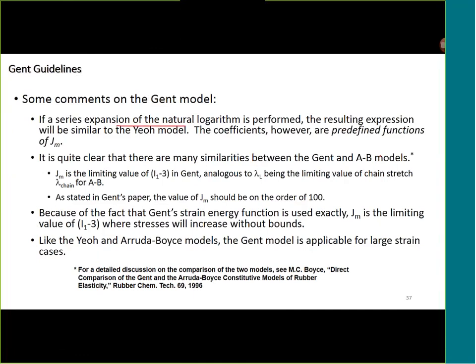Here the expansion is performed based on the logarithmic form, so that the resulting formulation will become similar to the Yeoh model, but the coefficients are a predefined function of the Jm. So it may not be suitable for all different types of stress strain behavior, but for whatever stress strain curve fits with this predefined function, this is a really good model.